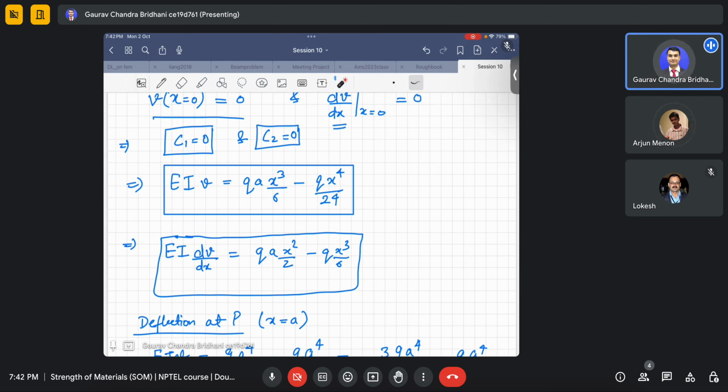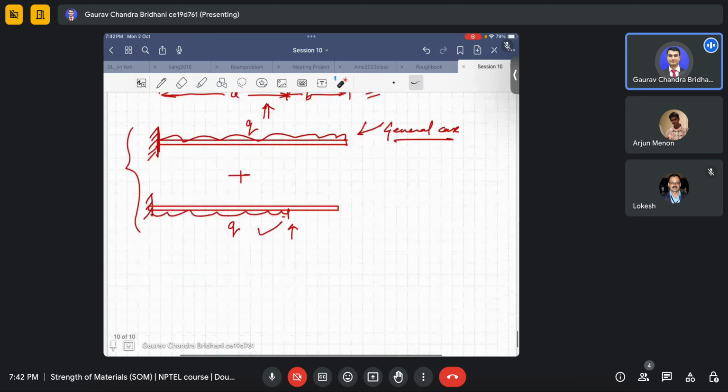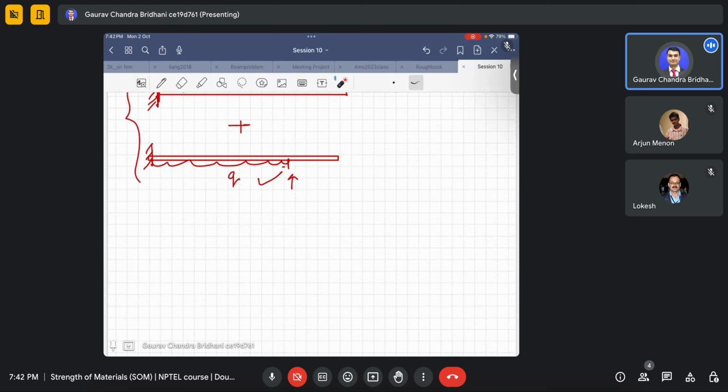That formula is only applicable when the load is at the center. As soon as this load moves away from the center, you can't apply the same formula. You have to find the deflection differently. So if P is acting like this, you can't do that, then you have to find it differently. But if only one load is acting, that is the point load, and only that load is acting, always the maximum deflection will be below P only, that is true.